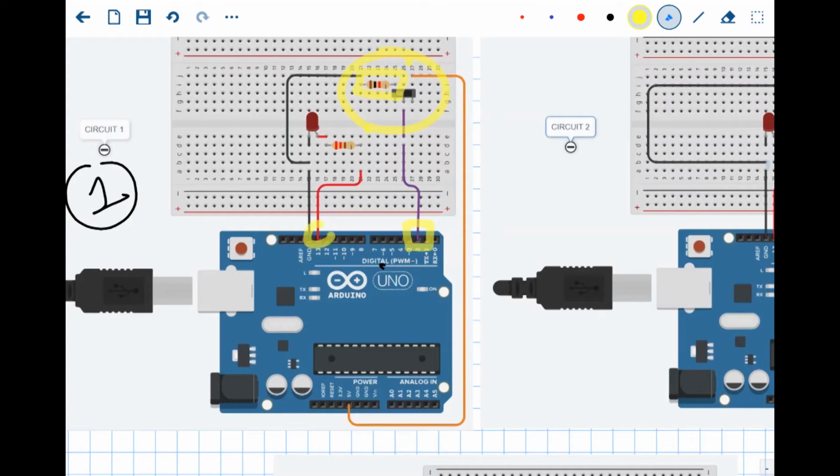Pin number 13 over here is connected to an LED to simulate an output device or a motor. The good thing about Arduino is that in the Arduino Uno board, there is an LED in the board, which is also connected to pin 13. So even if you do not have an external LED or anything, if you try to program pin number 13, what you will see is that for a high output at pin number 13, the LED will glow.